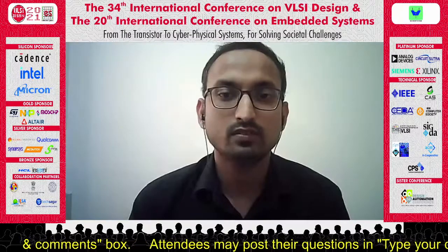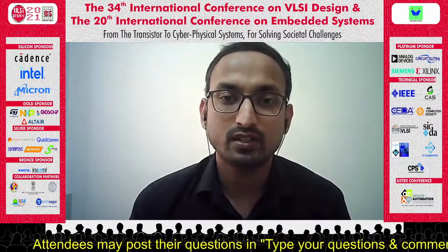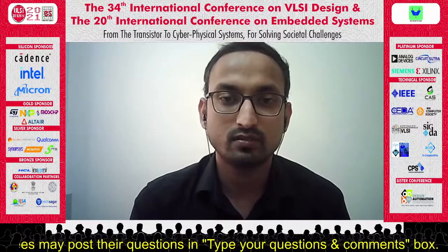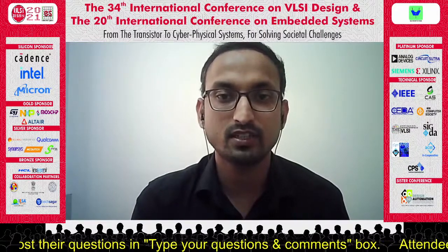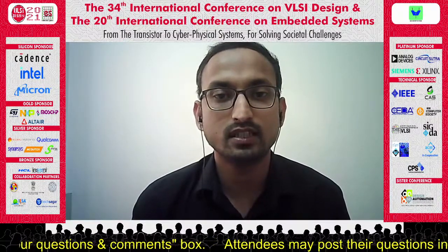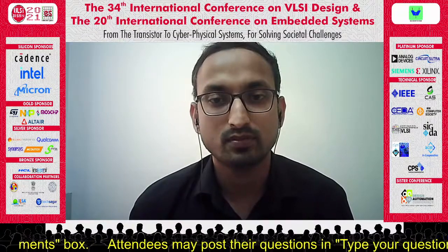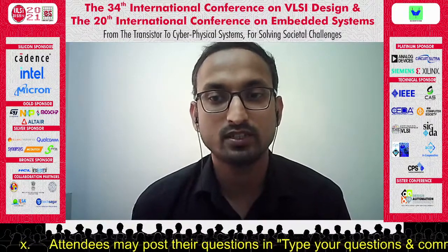Since the heating is mainly due to carrier-phonon scattering, and the maximum carrier energy is near the lower part of the extension region, but there are very few phonons there. There are very few carriers. So mainly the carrier-phonon scattering occurs near the drain extension and drain junction. That's why heating is highest at the edge of the drain extension and drain region.